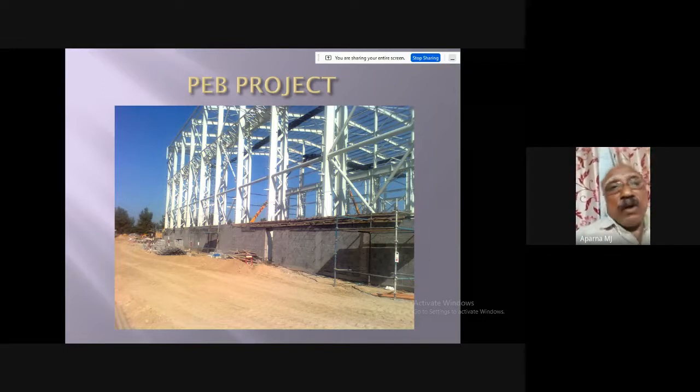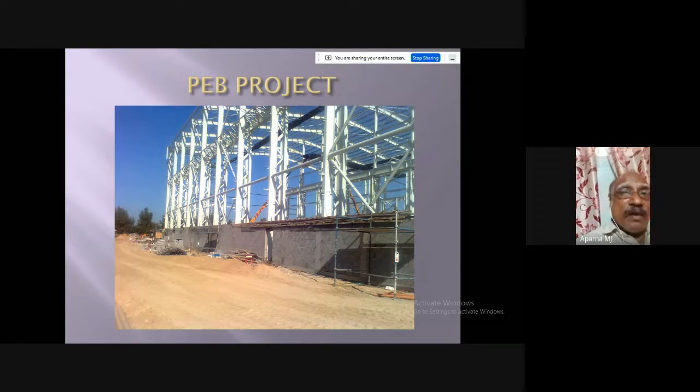If it is a small rafter, maybe 2-3 parts can be assembled at ground and can be lifted in a single lift. But if it is a heavy rafter, partially the first column will be erected, then the next rafter member will be connected, and using some scaffold or something, maybe we will give some prop support at the joining place.